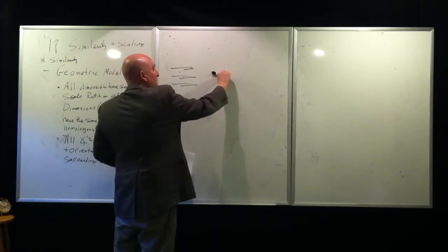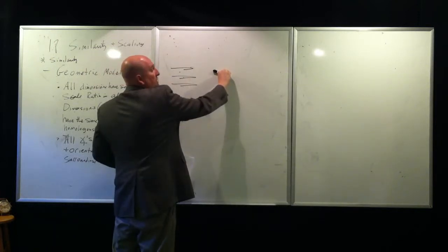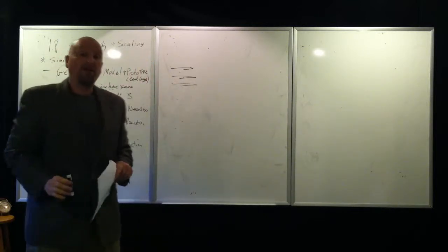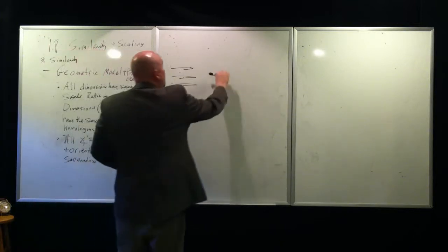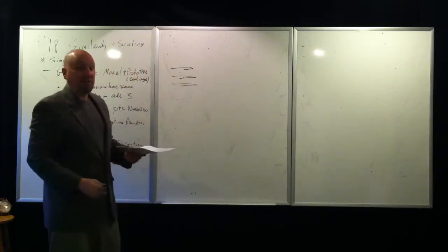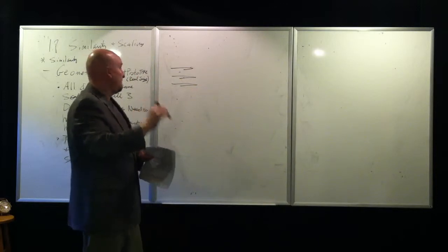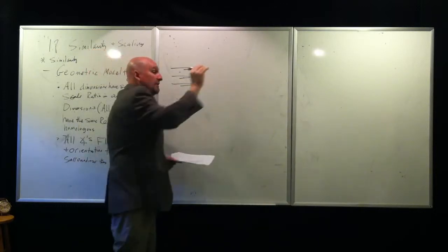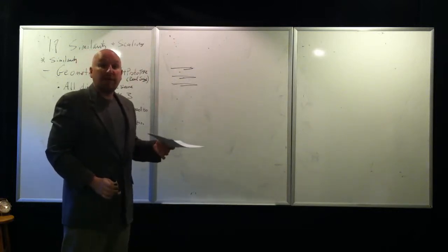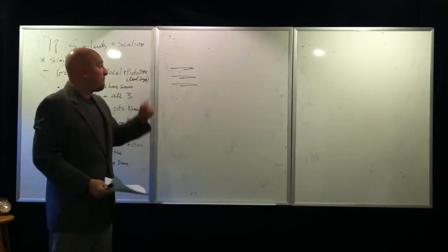Just like also, if this was to represent your airfoil, if it was at an angle of 20 degrees, your prototype would have to be valid for an angle of 20 degrees. And it has to be all angles. So the angle doesn't scale, but the angle has to be the same between the model and the prototype. And it has to be in the same flow and the same surroundings. So that's where your model design or experiment will be similar to the prototype.